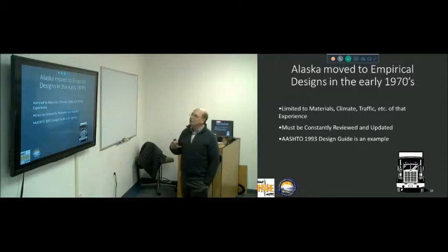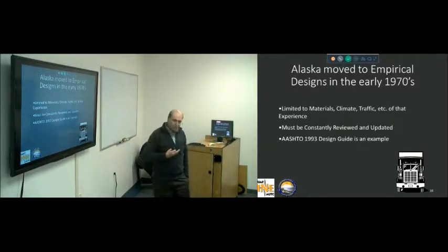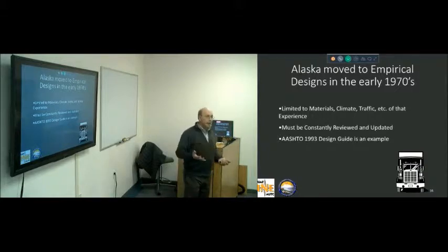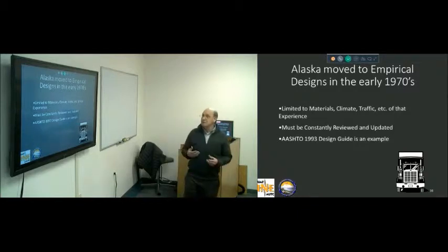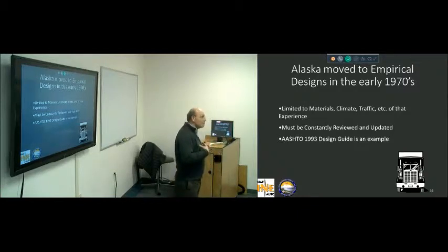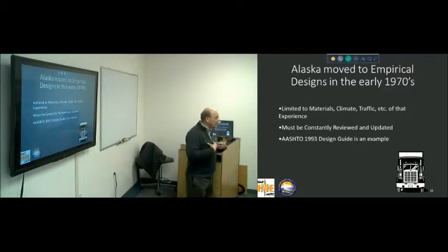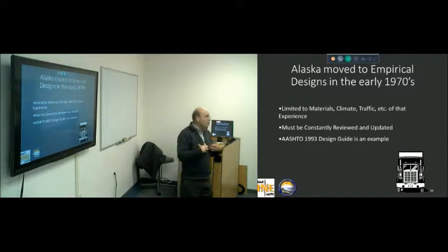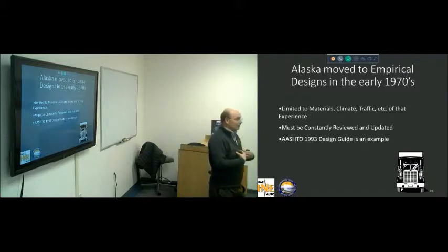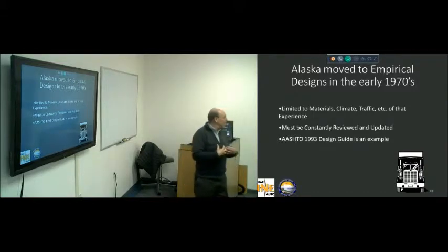And so we started looking at empirical design procedures. And empirical design procedures are really experience-based. And as such, they're limited to the materials, the climate, and the traffic that you have the experience in. My empirical design here in Alaska will not translate to Texas, and California's will not translate to Alaska, because it's not based on the experience of those that are using it.